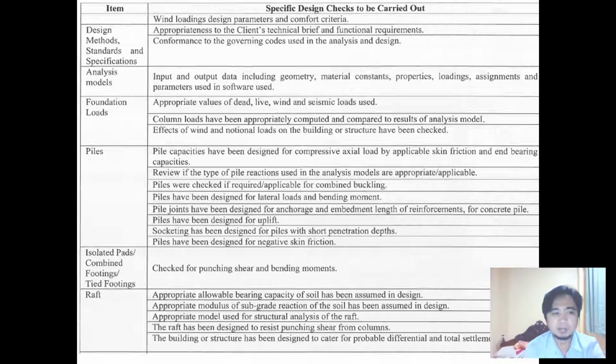So when we have a multi-story building, usually it will have a raft foundation because a higher level or more floors or more weight to be transmitted to the foundation requires more area of a certain pad or foundation pad.